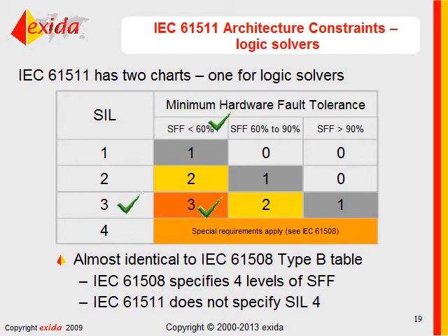What's hardware fault tolerance? Well, a 0 means you have a single channel of equipment. A 1 means you have 2 sets of equipment. A 2 means you have 3 sets of equipment. And a 3 means we have 4 sets of equipment. How'd you like to see 4 PLCs wired together? Oh my. This can be a real way to increase the false trip rate of any design.